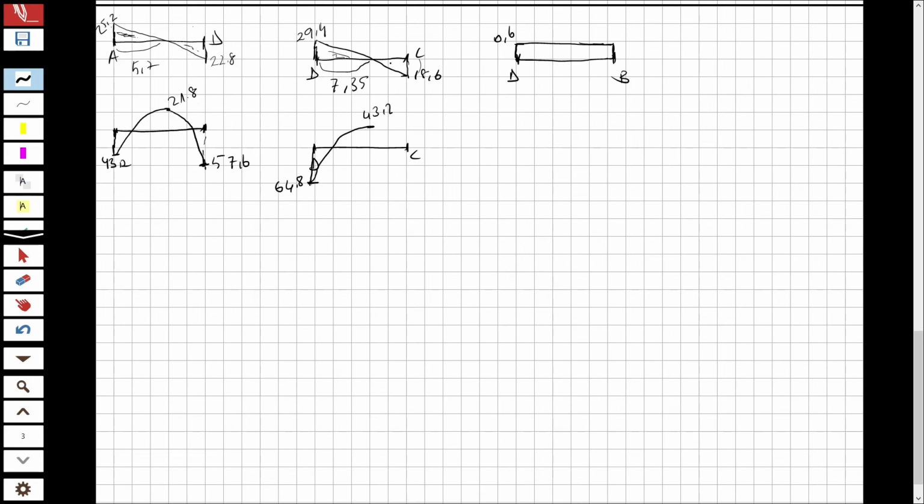And I'm going to go down at this amount of area. I'm going to decrease and come to 0 because this is a roller connection. In the roller connection, there is no moment, so it has to be 0. So I will decrease and stop with this one.